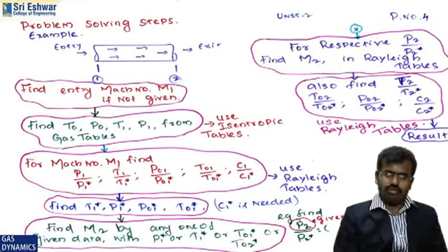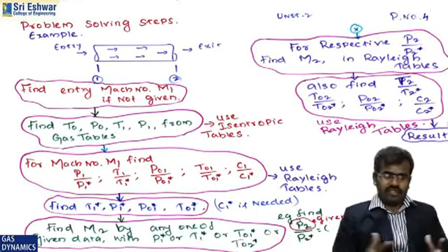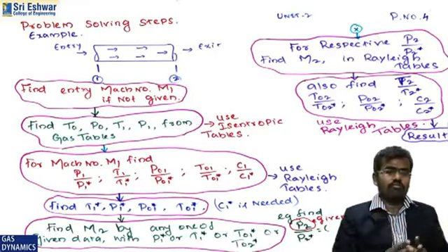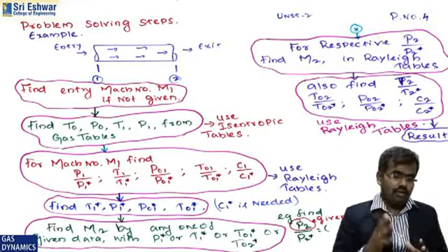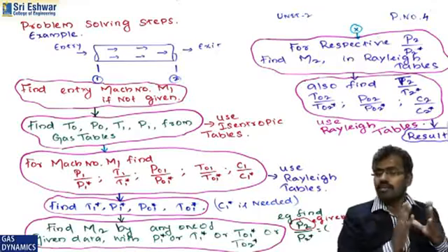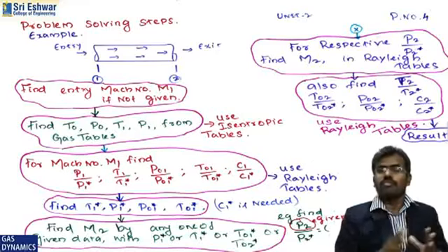By using these values. Right, now we know P2, say for example P2 is given. Now it is time to find the value of M2. How can we find M2? If they gave the value of P2, then find the ratio of P2 by P2 star using your calculator. Use your calculator to find the ratio of P2 by P2 star, then find the respective Mach number M. This is M2. Now we found M2. Now the problem is solved.